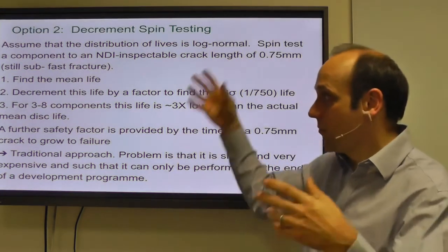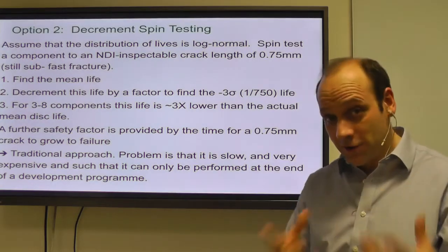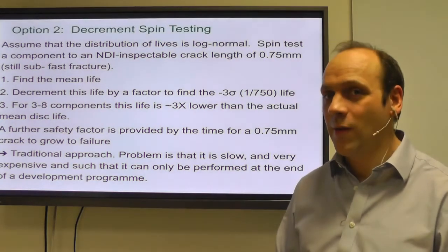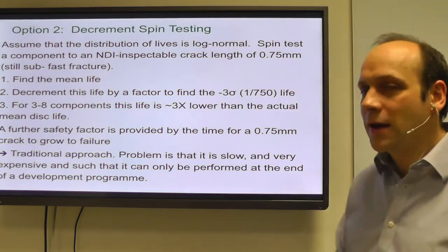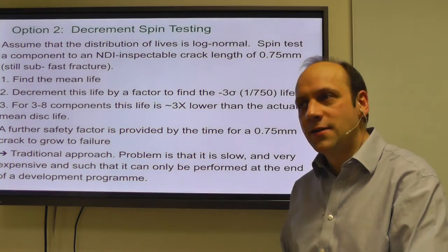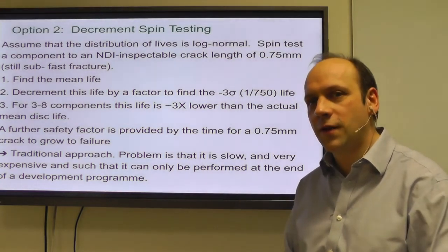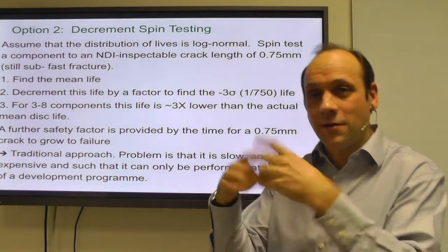You can only do it when you've got some discs that you've designed and you're willing to spin test. It costs you something like £250,000 per spin test, so this is also very expensive. And you can only do it once you've designed the discs and manufactured them at scale. So you can't ask yourself, okay, that didn't give me the life I expected. I need to get a bigger life, so I need to drop the stresses, so I need to redesign.